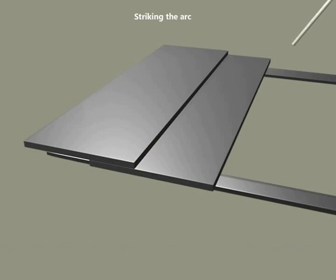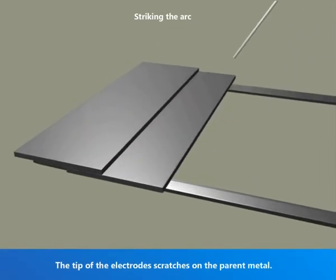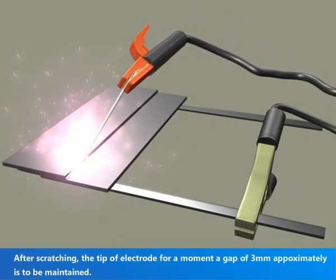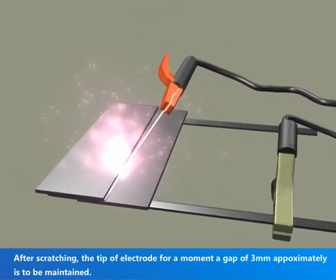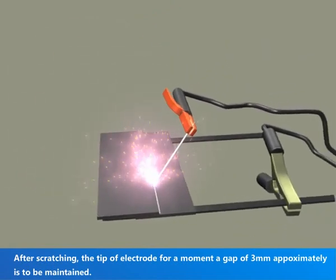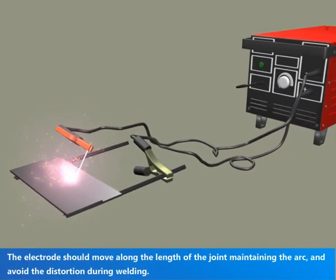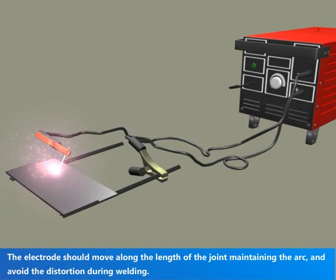Striking the arc. The tip of the electrode scratches on the parent metal. After scratching the tip of electrode for a moment, a gap of 3 mm approximately is to be maintained. The electrode should move along the length of the joint, maintaining the arc and avoid the distortion during welding.